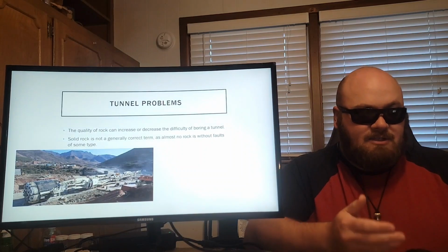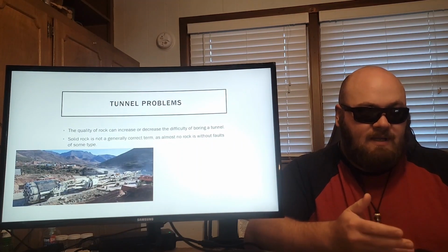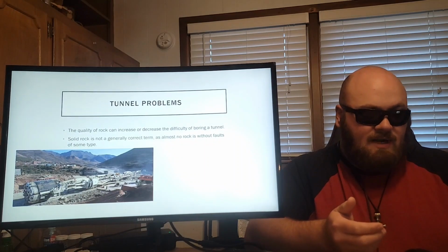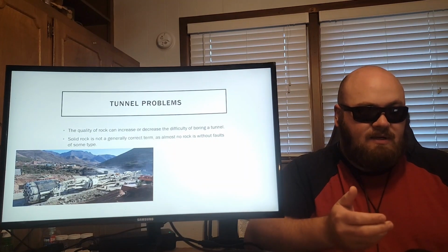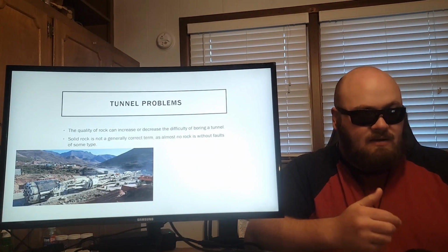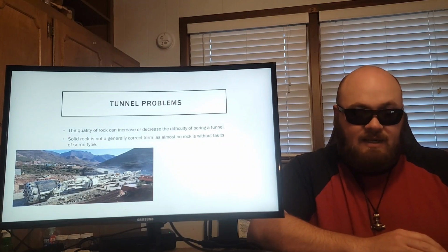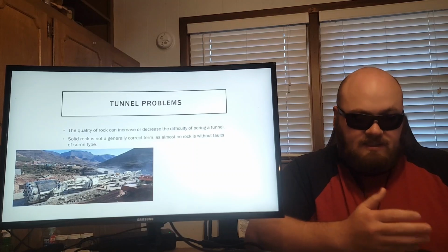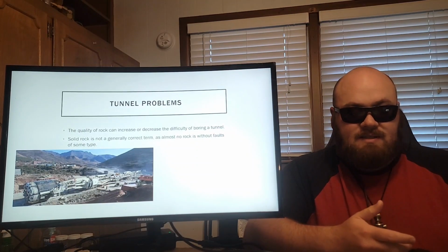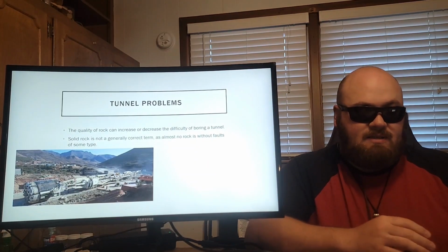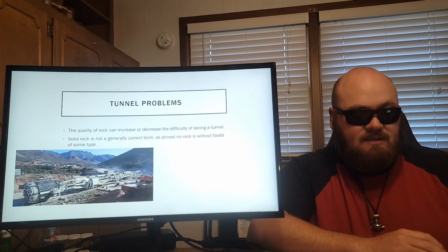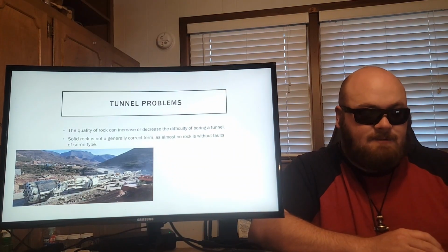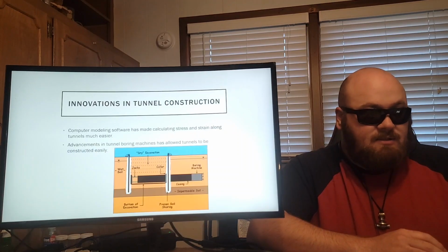The design and construction of a tunnel must account for the mechanical properties of the surrounding rock, which includes not only the aforementioned cracks and discontinuities, but also the weathering and deterioration of the rock, the number and type of layers in the rock, the strike and dip of these layers, underground water level, overburden, and the list goes on. These are all concepts that we have touched on at some point in this semester, from the strike and dip of a fault plane to the groundwater level of an area to the weathering of different rocks through chemical and mechanical means. All isn't doom and gloom, however,